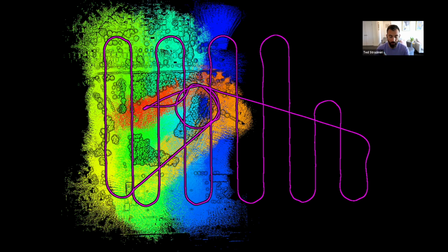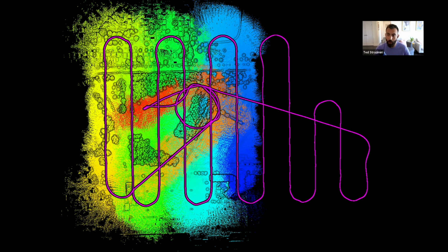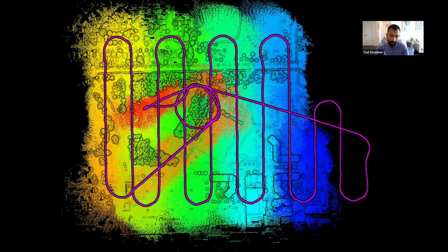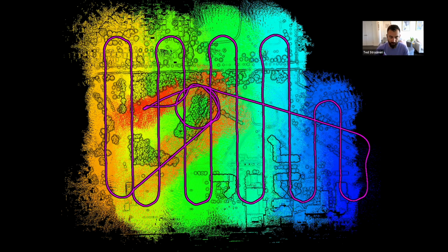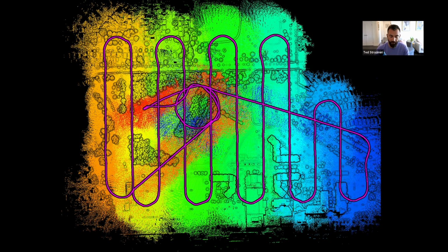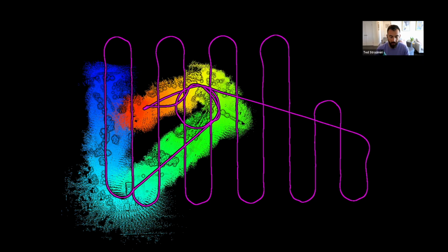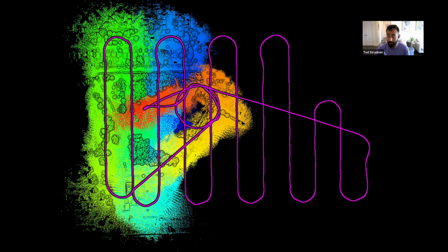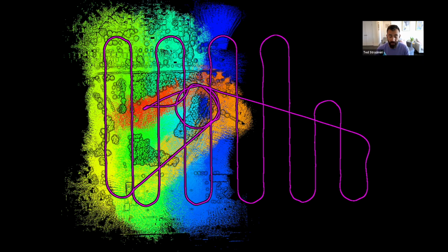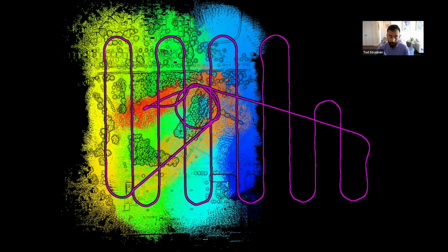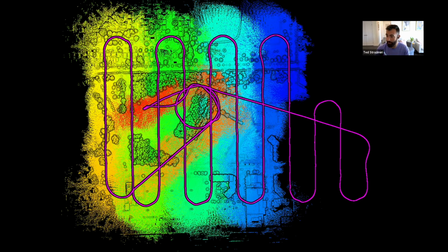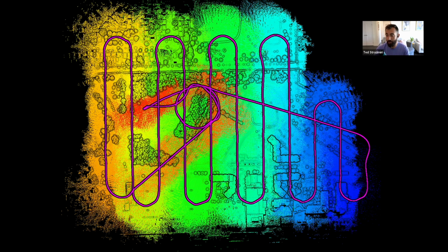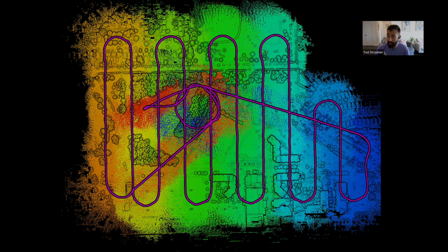So we have points that are overlapping, but they come in these swaths. And you can think of it sort of like a spray paint, right? You're spraying through as you're going, and where those points land, that's where you have them in your data set. But there's quite a bit of those points that are in areas that are not favorable to keep, such as the turns, right? Those are some pretty high dynamic forces in that moment. And then also the section where, in this case with the Wingtra, is the transit from that vertical takeoff to that forward flight. So we want to cut those out because it's just too much, and it actually can reduce the quality of the overall data if we leave it in.